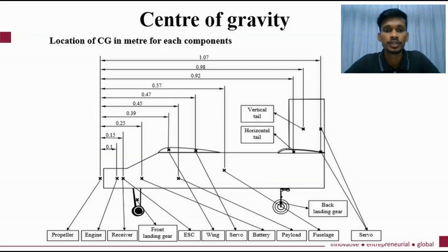The center of gravity of an aircraft is the point over which the aircraft would balance. The center of gravity affects the stability of the aircraft. To ensure the aircraft is safe to fly, the center of gravity must fall within specified limits. There are four important center of gravity locations determined for the analysis of balancing and stability: maximum weight CG, empty CG, aft CG, and forward CG, which will be shown in the following slides.